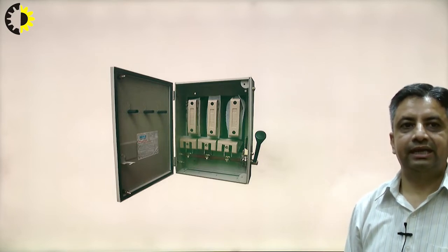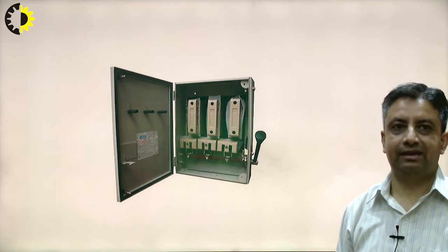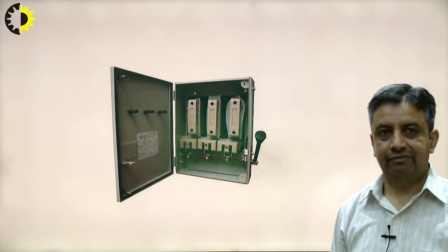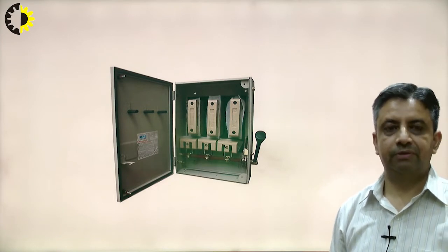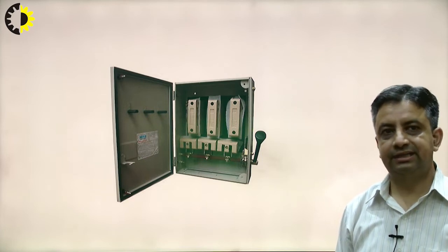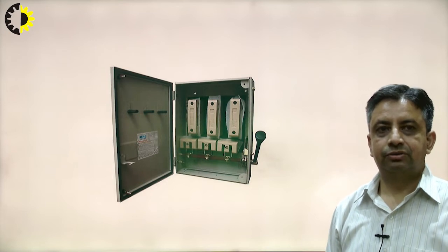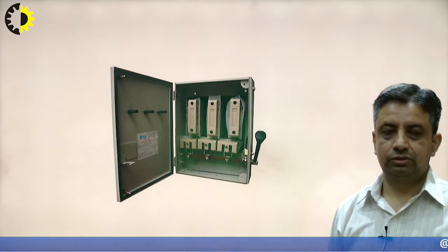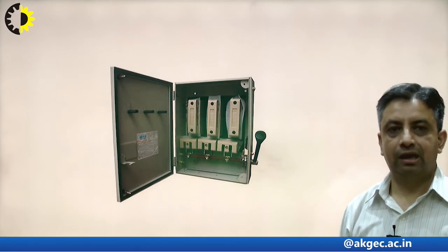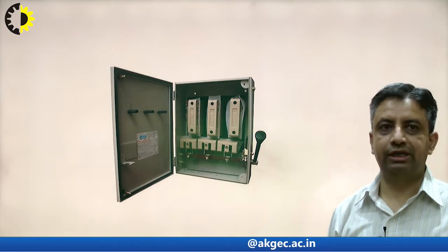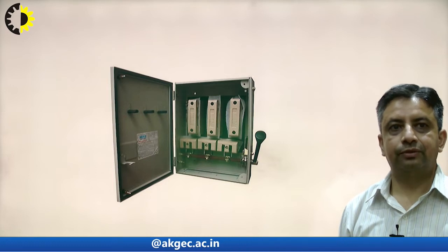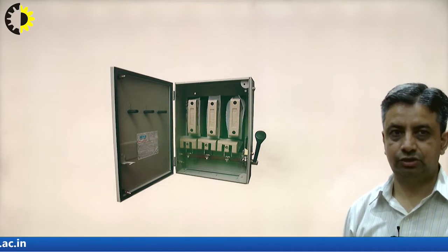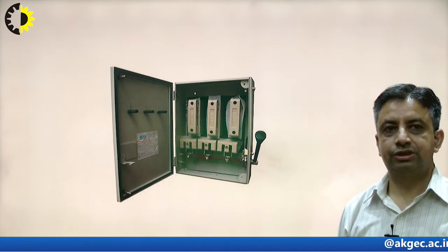As you can see here, this white portion is also called the KitKat. Inside this KitKat, we generally have a wire, that is a fuse wire. Whenever the current exceeds its limit, this fuse wire will blow up and disconnect the supply and the load. Thus it will protect the load from any unwanted situation like overcurrent or a faulty situation, that is the short circuit condition. Here, as you can see, we have one lever. With the help of this lever, we can switch this box on and off. So it is generally called a switched fuse unit.